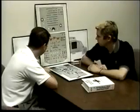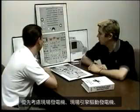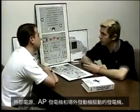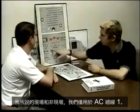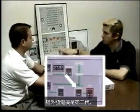Electrical panel. What is the electrical priority? The priority is on-side generator, on-side engine-driven generator, the external power, APU generator, and off-side engine-driven generator. What I mean by on-side and off-side, let's just use AC bus 1: the on-side generator is Gen 1, the off-side generator is Gen 2.